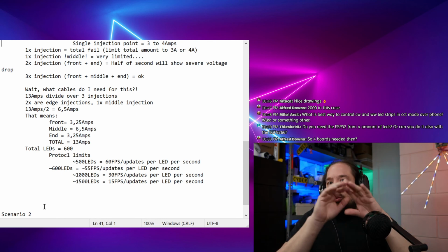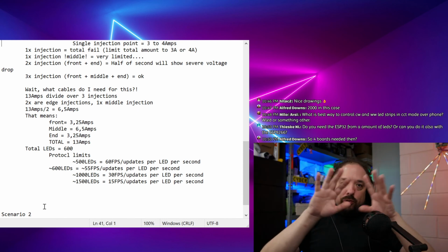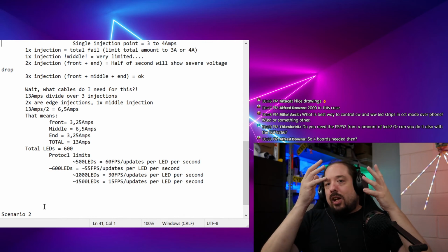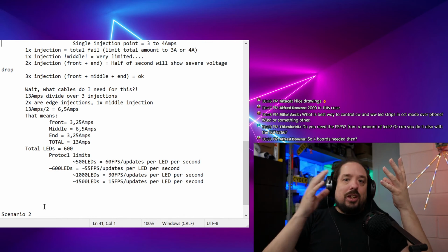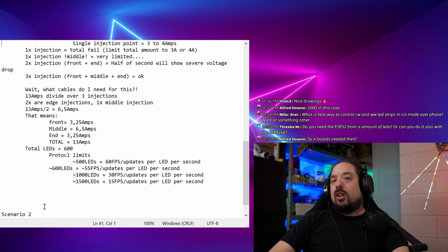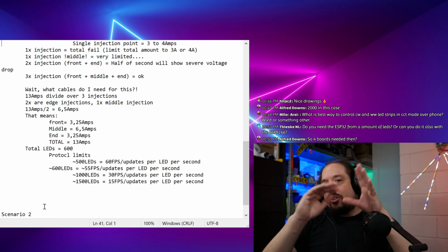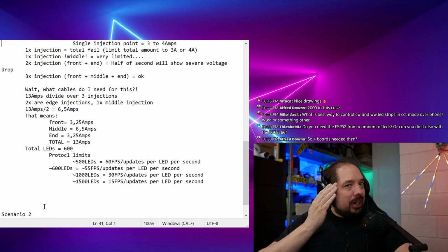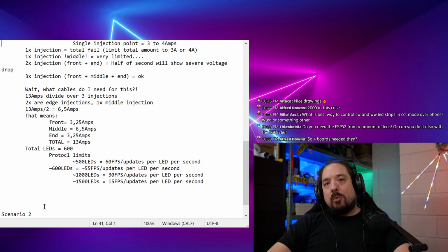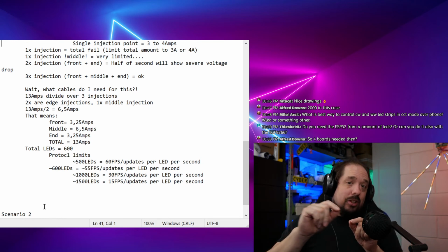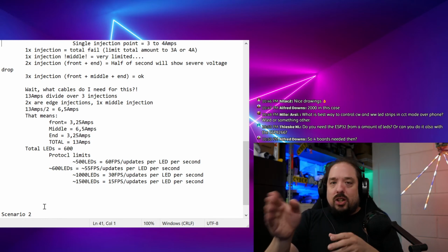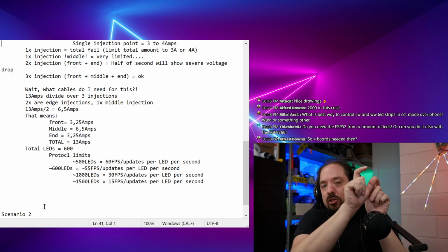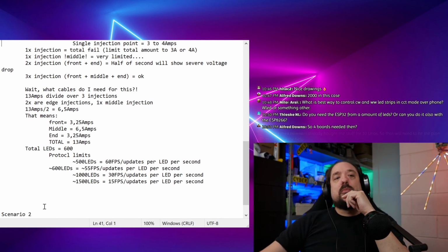So all effects will run fluently over the 4 different strips as if it's one strip, even though you're using 4 output terminals. If you're using 4 controllers with the sync option and stuff like that, it won't look that great because the sync option basically sends the same effect to that other controller. It doesn't sync them so they have a smooth transition between the two.